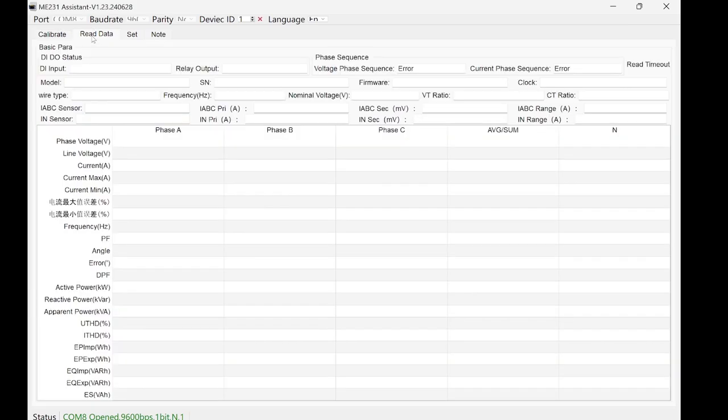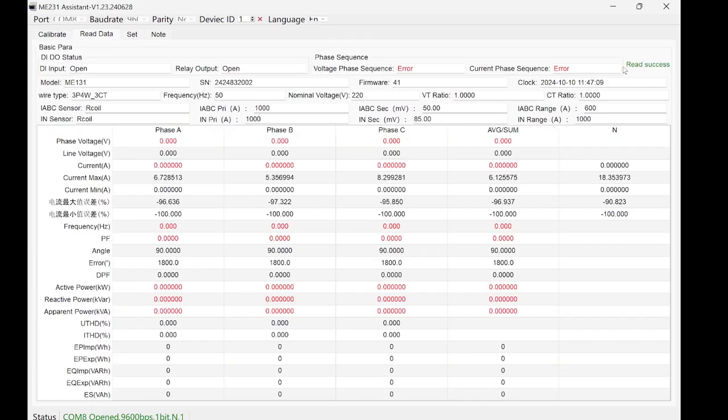On the second tab, if you give it some time, it will read all the values from the meter. So if there's any voltage or current connected, you'll see that here, and you'll see the current settings of the meter. For testing purposes, we'll be using the serial number. I'll note this number down and see if we can read the same value through Modscan and through Node Red.